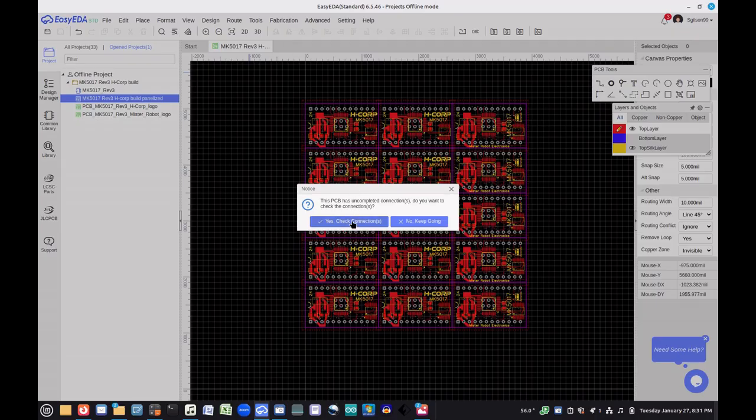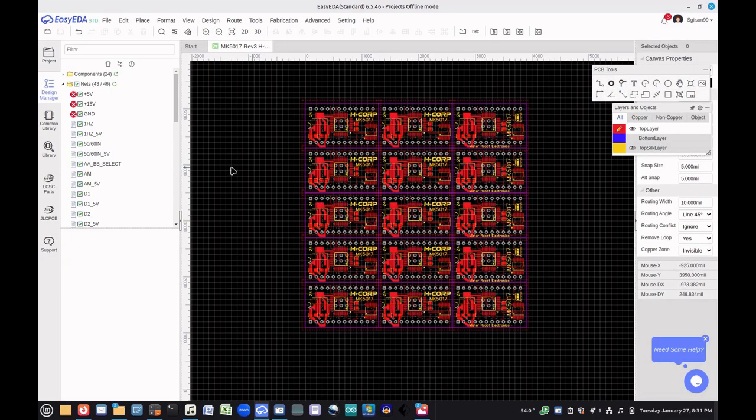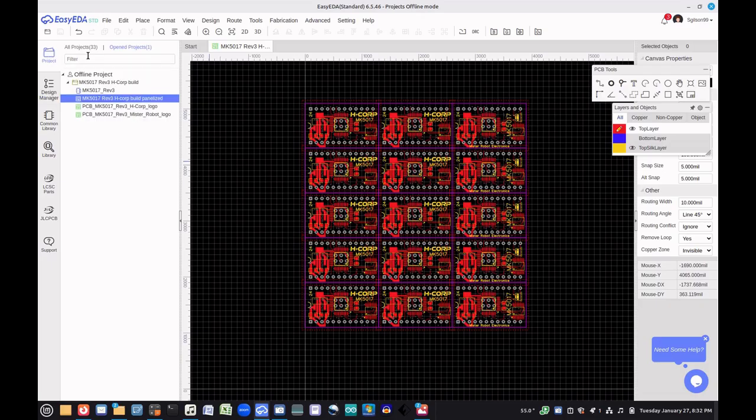You can check connections, in other words, do a DRC. Let's do it and see what happens. And you'll see you've got some warnings, I guess. You have no DRC errors. Okay, well, that's good. These warnings are fine. I've checked them before.